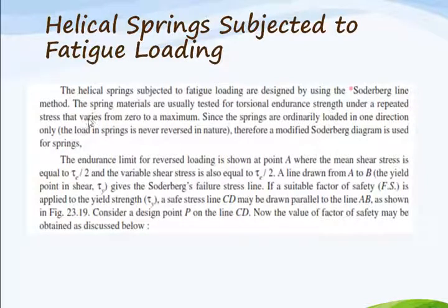The spring materials are usually tested for torsional endurance strength under a repeated stress that varies from 0 to a maximum. Since the springs are ordinarily loaded in one direction only, because there is no reversal loading, a modified Soderberg diagram is used for the springs.